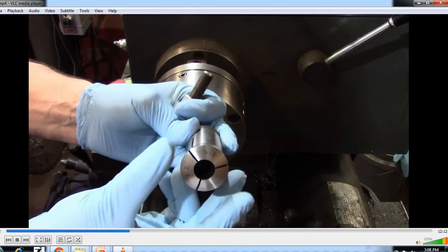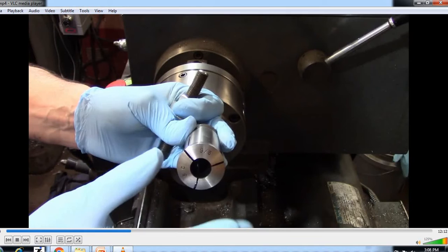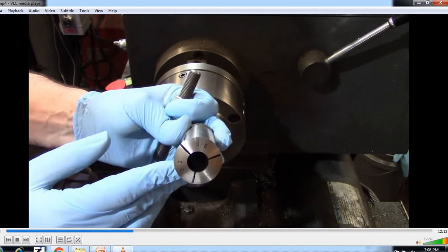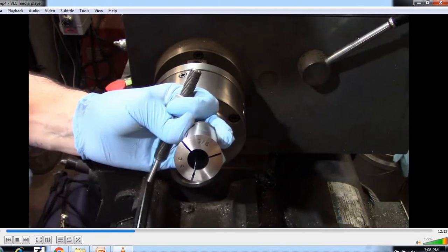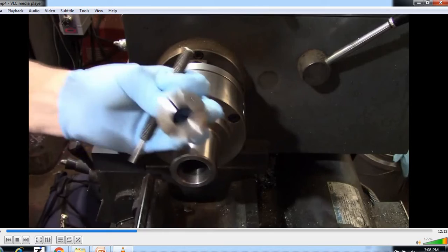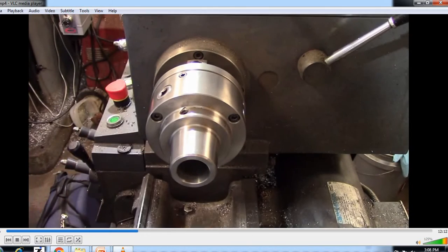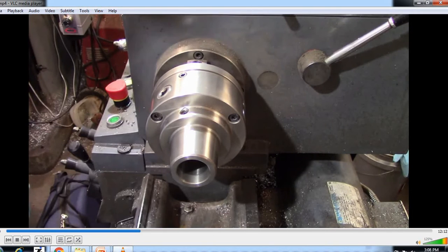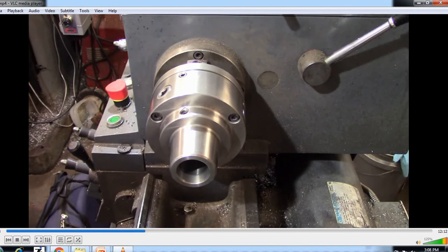On the downside, they have a limited clamping range of only about 0.5 thousandths of an inch, so the part must be very close in size to the collet diameter, and it also takes time to change collets so different diameters can be held. There are other types of collets available to use on lathes that have either different holding styles or larger or smaller capacities, but 5C collets are the most widely used by a very large margin.